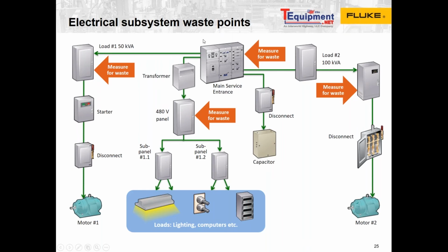And if you are trying to figure out which circuit branch, so each of these 4 branches, this is just an example, you might have many more branches or fewer. Each of these circuit branches consumes a fraction of that total power that you might be measuring right here with a Fluke power quality tool.